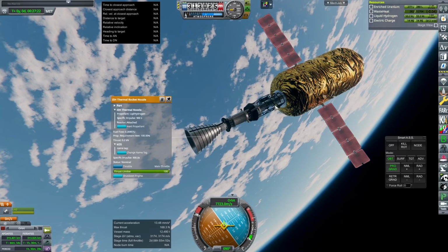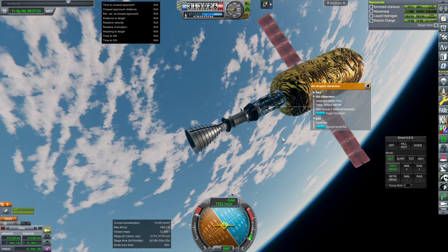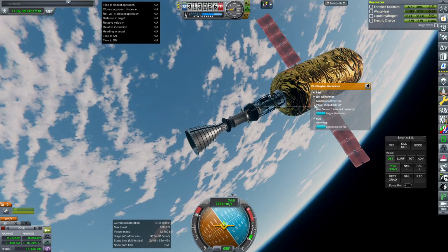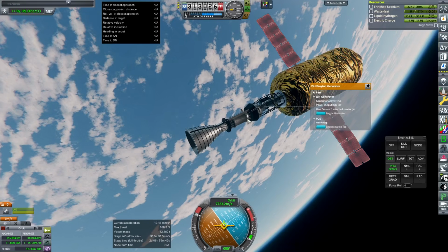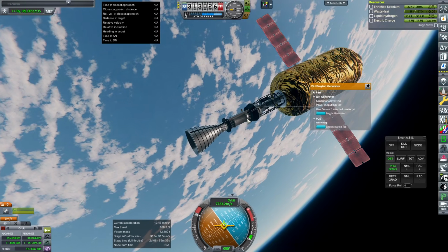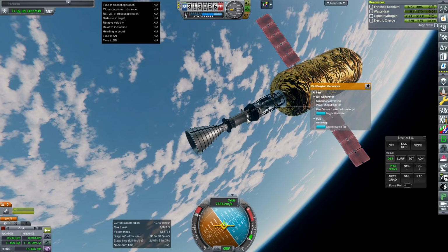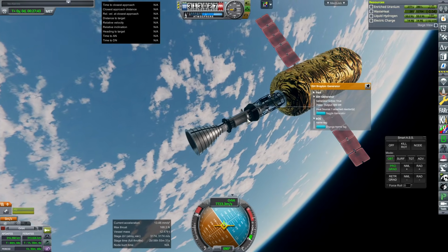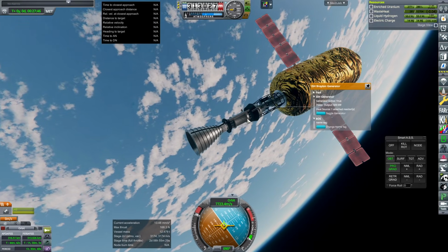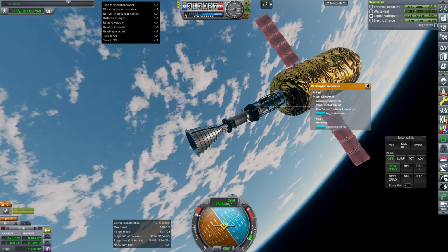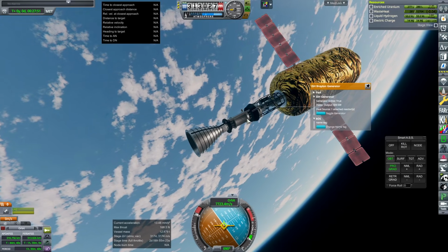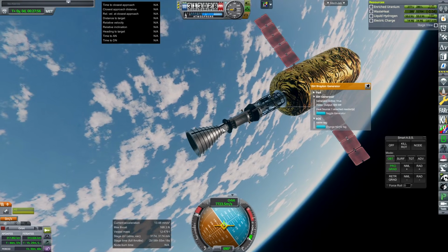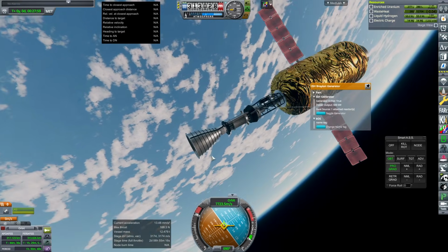But there is another way to get more thrust here. Shut down the generator, right? Right now, we've got 1.5 megawatts. Of that, 600 kilowatts is going to the generator. Basically, the generator is taking the 1.5 megawatts, but it only has an efficiency of 33%, I guess it's 30% or something like that. Anyway, it's got its efficiency, and then it's going to send the rest of the waste heat through the nozzle, is basically how this is working.